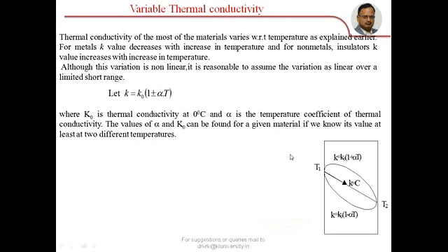Now let us come to the analytical part of it. As we have seen from these graphs, thermal conductivity of most materials varies with respect to temperature. For metals, K value decreases with increase in temperature. And for non-metals, insulators, K value increases with increase in temperature.